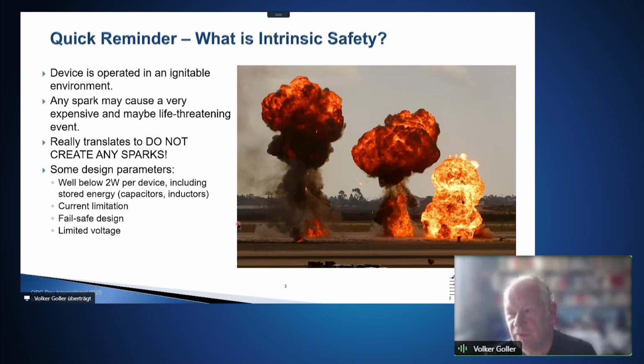So the overall power envelope includes this stored energy, because stored energy can also do harm. So there is a certain need for current limitation. It needs to be a fail-safe device design, and it has a limitation in the voltage. You can't go in with 24 volts or something. You have to be careful.